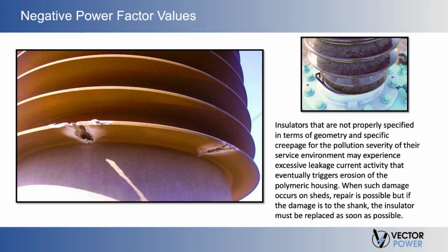Make sure the surface of porcelain bushings are clean and dry to minimize the effects of surface leakage. Sometimes it's also useful, if we do have to test on a high humidity day, to have fans or high airflow, again, to try to keep the surfaces as dry as possible. Now, make sure that all items such as wooden ladders or nylon ropes are removed from the equipment to be tested and are brought out of the electrostatic interference fields that could influence a measurement.